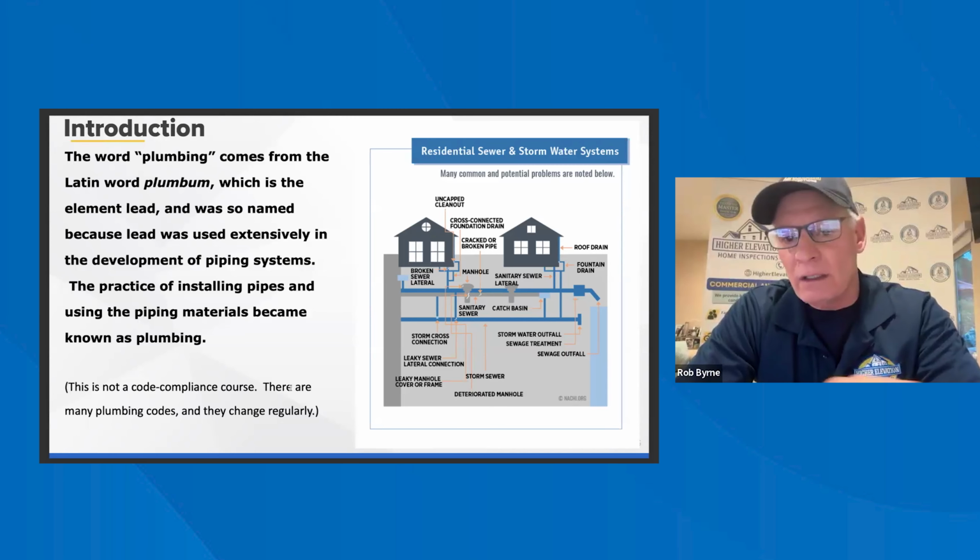Just on that valve, you check to see if it's leaking or corroding. You're not going to open it up, but you could suggest to your clients, if they want to flush it out, they attach a garden hose and let it go down a drain, etc.